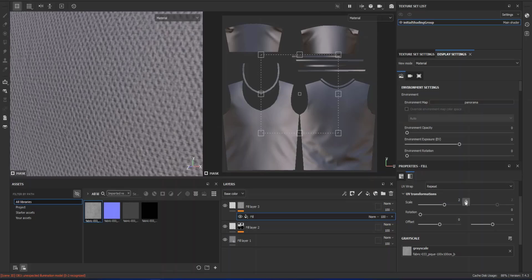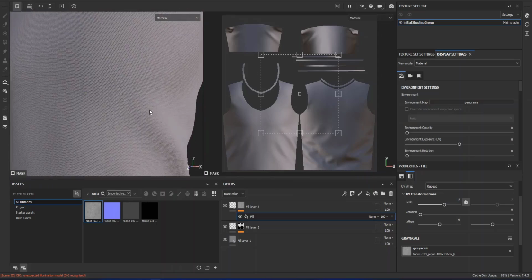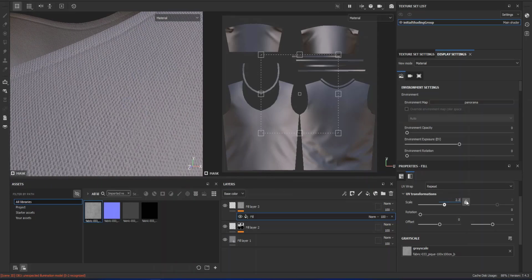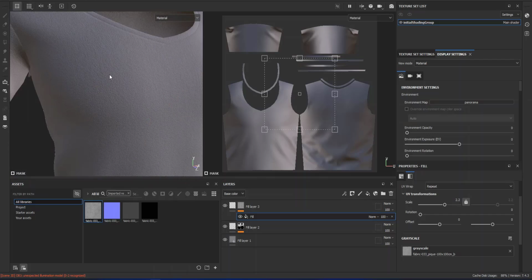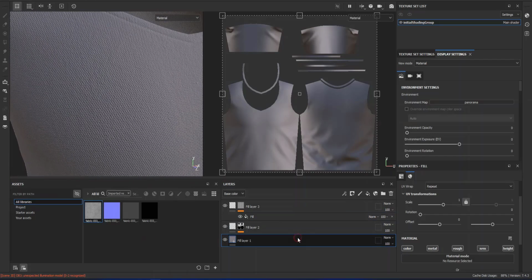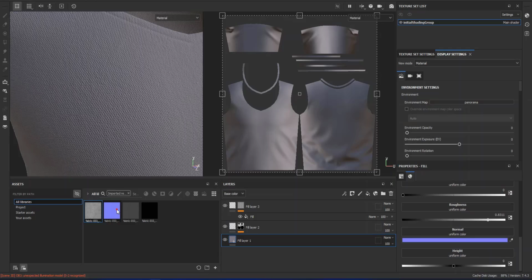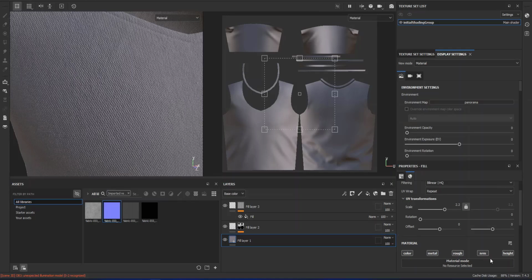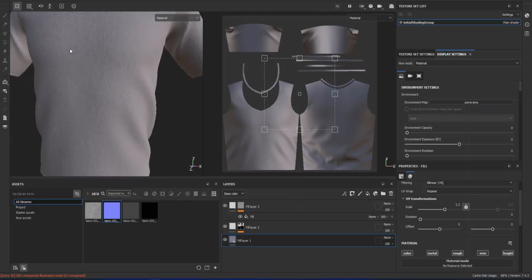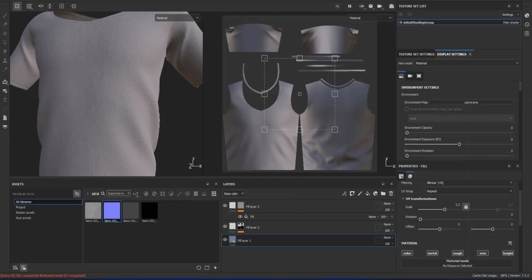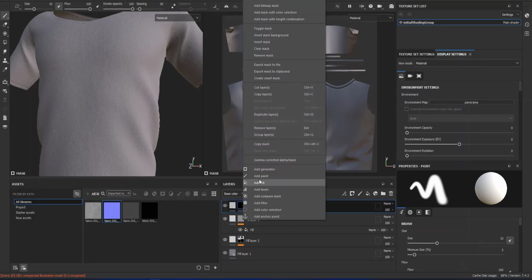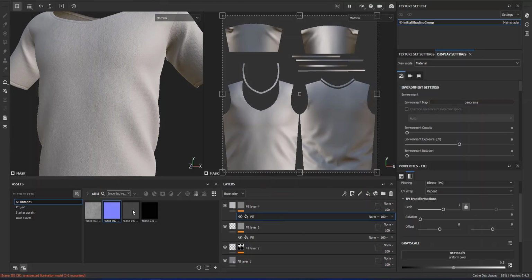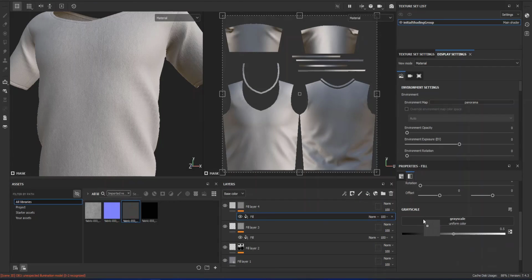The warp filter is used to create disorder and imbalance in the environment. This filter can be used so that the material is not homogeneous. Other filters, such as blur, sharpness, bevel, etc., can also be used, and by combining these, we can achieve the desired material. To add clearer noises and irregularities in the material and add fine and messy details, it is better to use noise textures or grunge and adjust them manually.